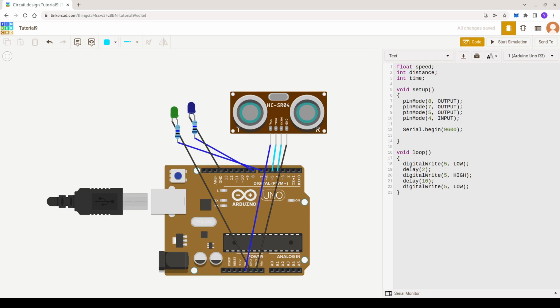Now what does the code over here do? Consider it like a switch, guys. As I said, first it is off. We are telling Arduino because Arduino is foolish. It is just a component, so it doesn't know, and for that we are telling it: first of all, it is low. Now, you saw that because we were not doing a delay, we couldn't see the changes being reflected. So here we are giving a delay before it is getting high again, right? Delay of 2, because when it runs again, it needs to stop for a bit. That's why, delay of 2 milliseconds.